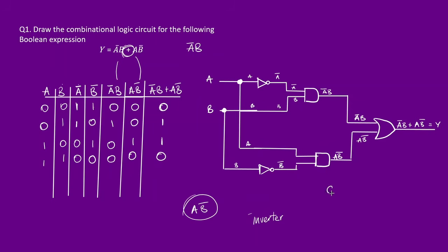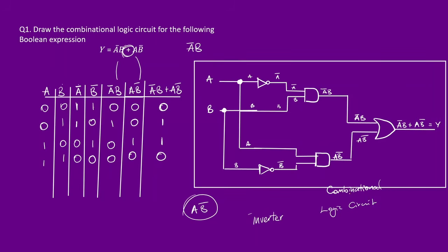So this is our combinational logic circuit, and it looks pretty neat from afar. Okay, really fancy stuff. So we can see it's not particularly difficult to design. Same thing with logic gates. You just have to be careful when designing your truth tables. If you've got a negation, create a column for your negation. Treat each of the terms individually. Then you perform the final operation. The same thing goes for here. You have to really be careful as you're designing your logic gates. Remember the difference between AND and OR gates, how to add them together.